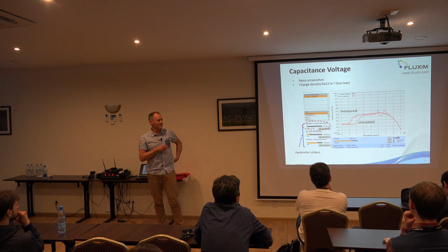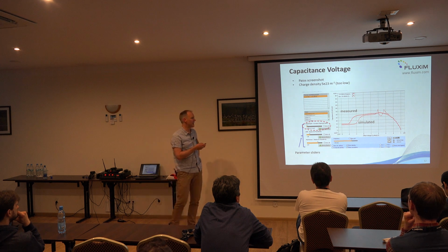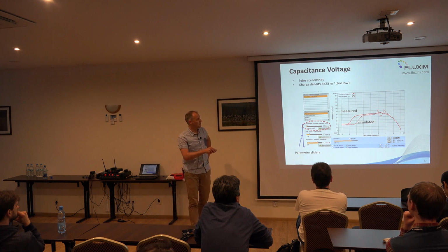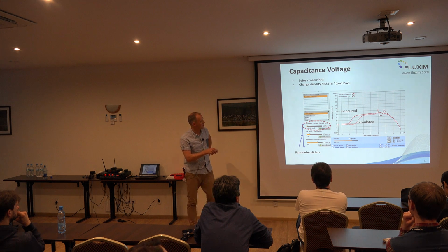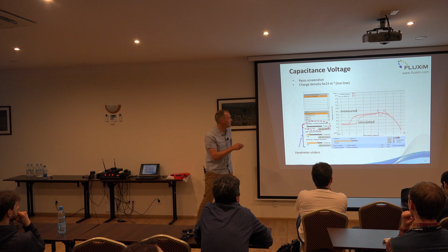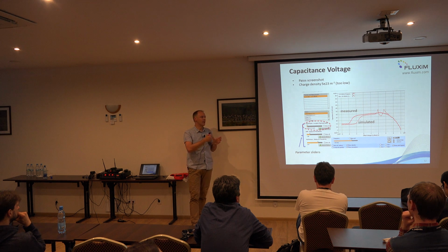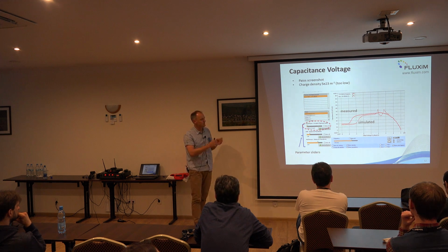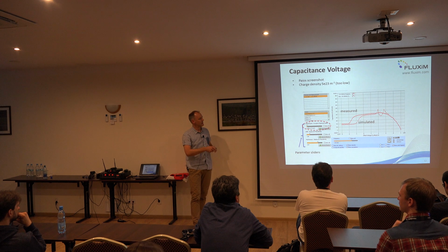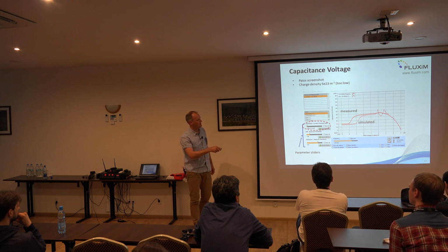So this is a kind of 30-year-old OLED type, this Kodak OLED type, where at reverse bias you have a geometrical capacitance value. In this number here, 15 nanofarad per square centimeter. That's the geometrical capacitance, so the parallel plate capacitor. If you believe the OLED is empty, no carriers inside, then for the given thickness of organic layers, this would be the expected geometrical capacitance value.